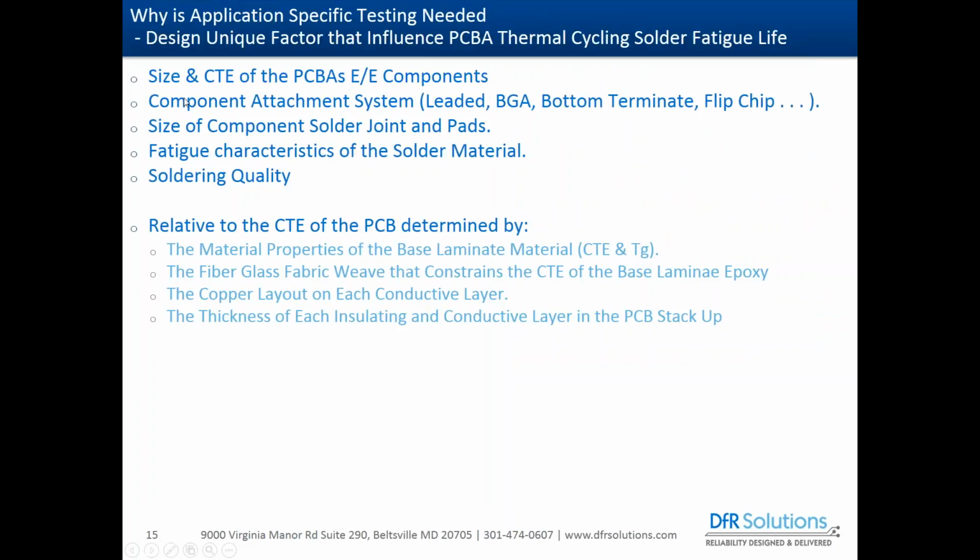So again, why is application-specific testing needed? Well, it's because, as I just said, there are so many different sizes of components with different coefficient of thermal expansion characteristics relative to the circuit board that they're attached to. There are many different kinds of component attachment systems: leaded component, ball grid array, bottom terminated, flip chip.